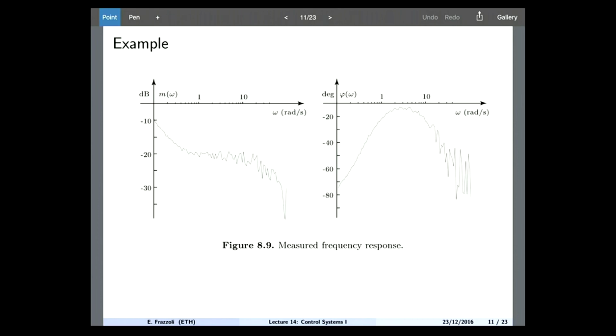Typically what you may do is you get a system, for example, you get your seesaw, don't believe what the TAs are telling you, and don't believe what the professor is telling you. But take the system and apply a sinusoid. We know that if you apply a sinusoid and your system is stable, you will get another sinusoid, the same frequency, different phase, and different amplitude.